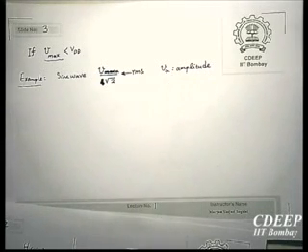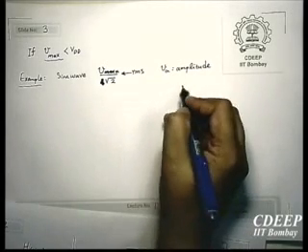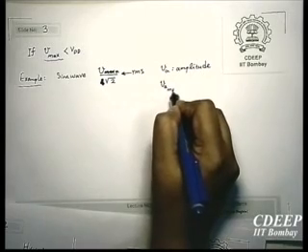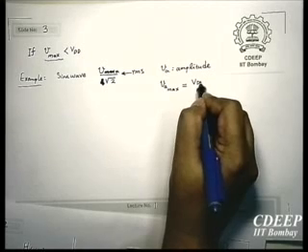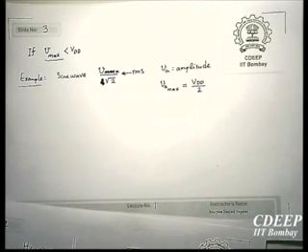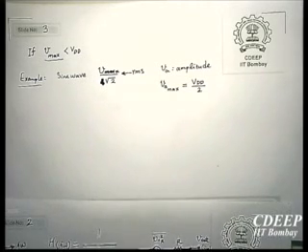Say for example you apply it to the input of this RC filter. How much can this be? The maximum amplitude you can get is limited to VDD. And if I have a single supply system, then Va max will be VDD by 2. Because I have a linear system, my sine wave should be symmetrical. I cannot clip it from one side, otherwise it's fully nonlinear. To have this linear system, I should have maximum amplitude limited to this value. Therefore, we now have a max and min for the voltages which can practically be used.